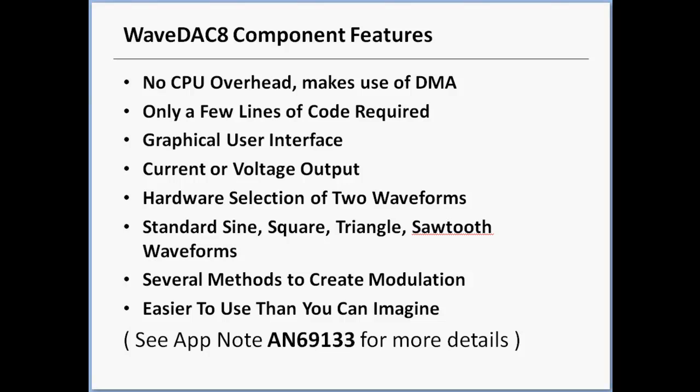It can be configured for either voltage or current output and supports all ranges that the standard IDAC 8 and VDAC 8 PSOC Creator component support. One of two waveforms may be selected between with the wave selection input. This makes FSK modulation very easy. The sample clock may be generated internal or external to the component depending on the application.